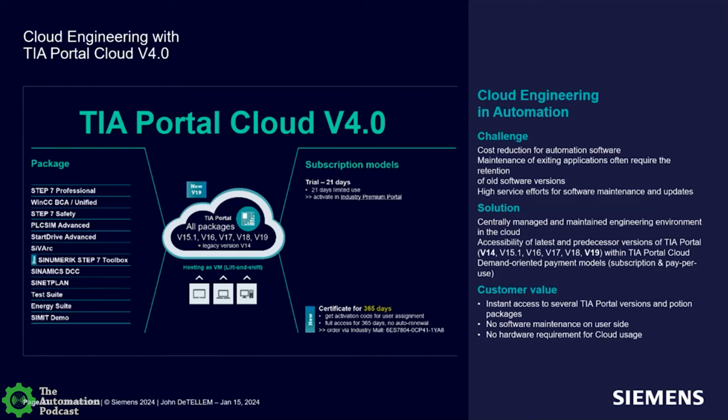When I'm in the 365 software, I have a cloud connector, so I can actually connect through the cloud to my local machine, set up some secure certificates to verify who I am and who the cloud is, and tie it directly to my PLC. Yeah, that's the piece that allows you to work in the cloud, but communicate to the PLC in front of you.